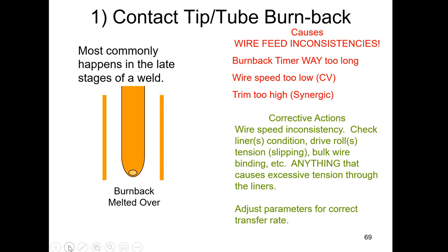Now I'm checking the consistency and the flow of the pressure and resistance at each one, making sure that the wire can slide back and forth at each point. I've learned many times doing this exercise that there are certain choke points where the whip or the conduit is giving us all kinds of problems because of the location. Just knowing this often figures out why this particular weld is always a problem.